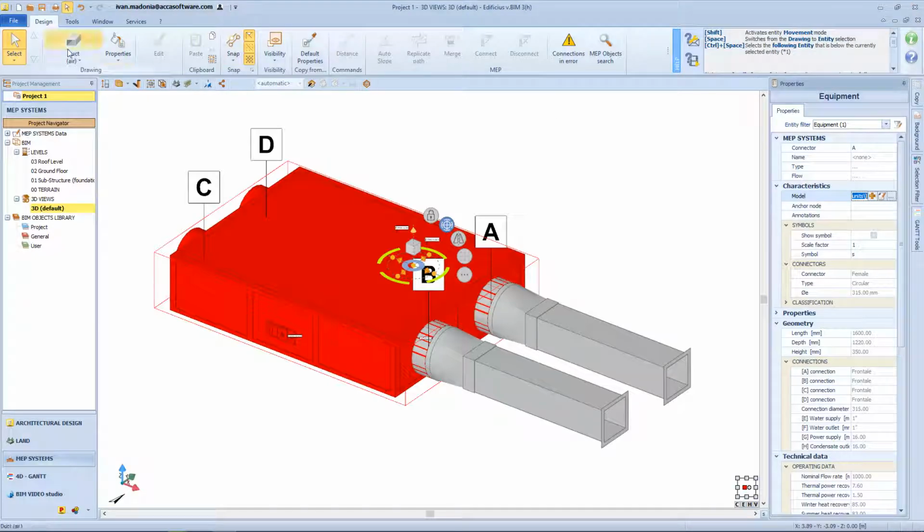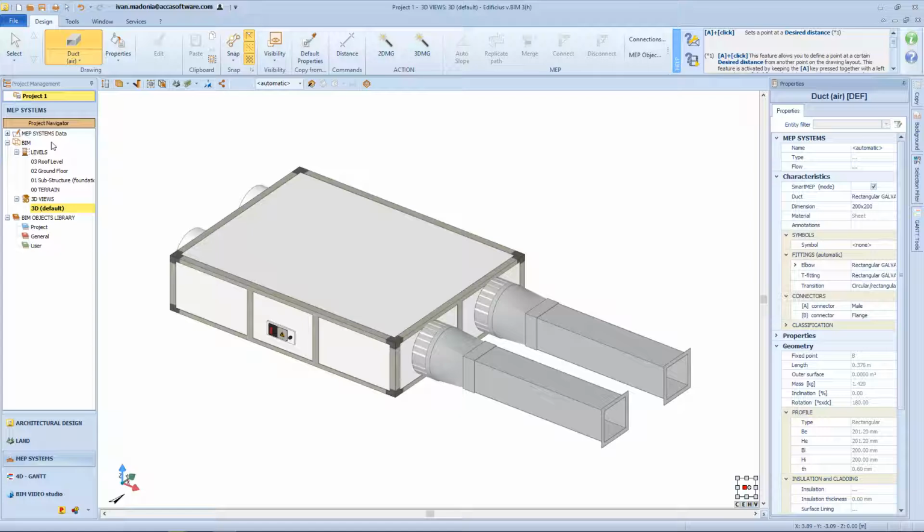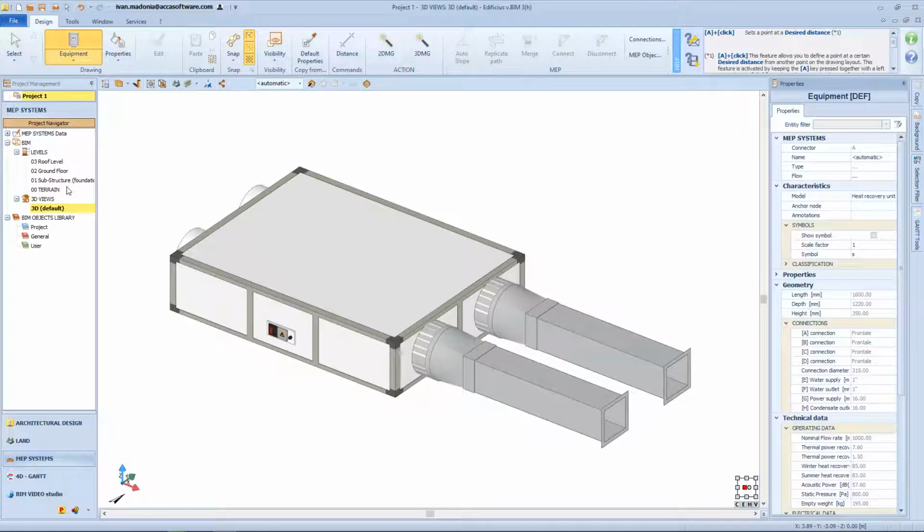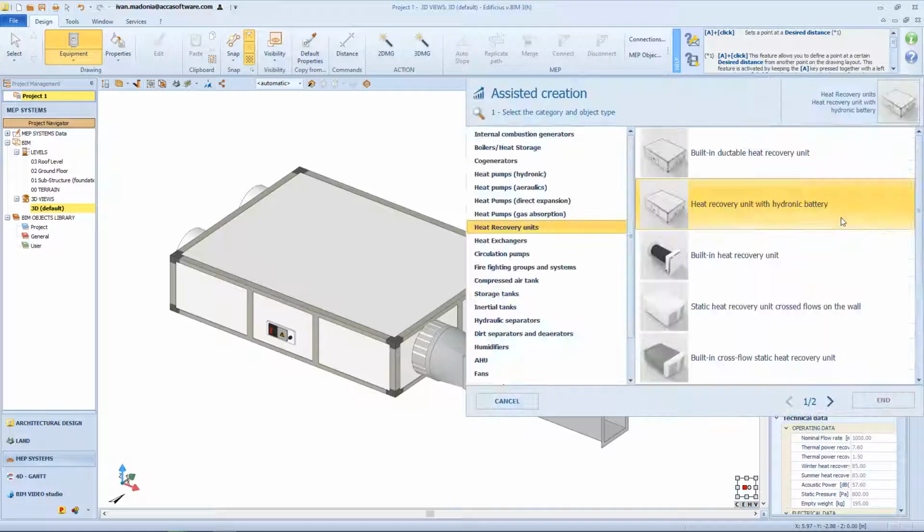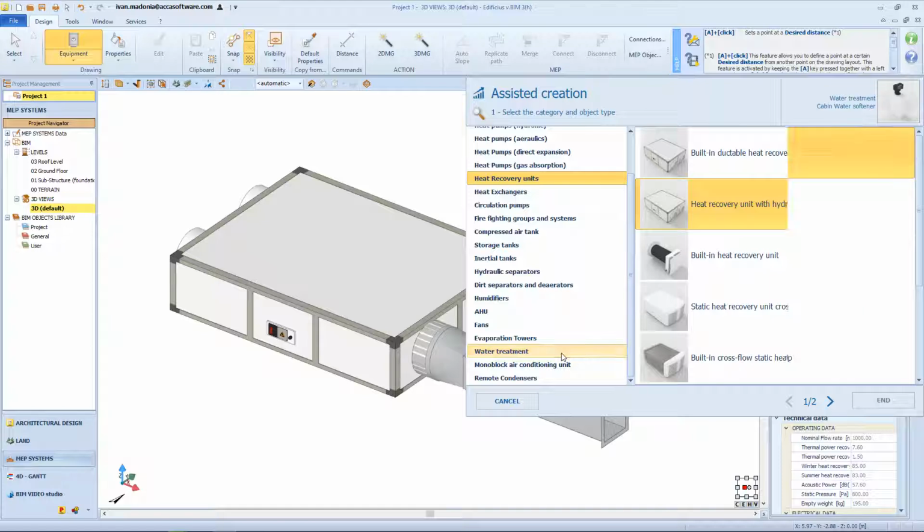Similarly, in the case of connection entities, you can select the same button in the Pipe field to access the libraries, to choose a different material for the pipe or duct and a different profile shape. You can choose the BIM object library from which to select the object. By choosing to remain in the project library, in the case of a parametric MEP object, all the elements belonging to the specific category from which it was chosen are proposed.